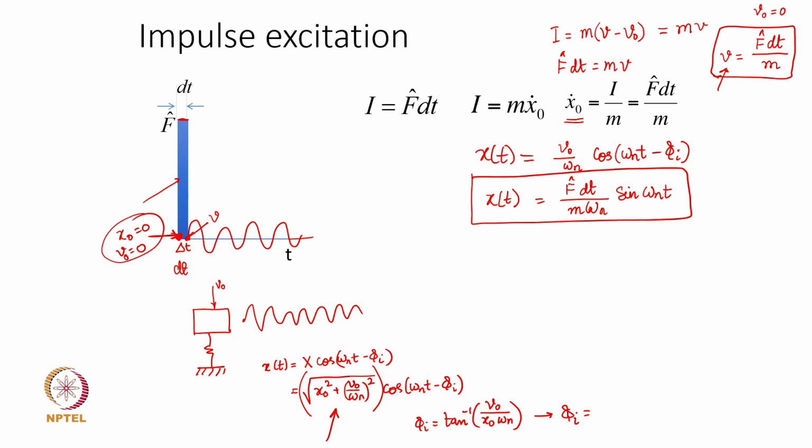The finer the dt value, the larger the amplitude, because this value is your amplitude. For the same f cap, if you reduce that delta t, the amplitude will rise; the larger you take it, the more it will reduce. That is how the response can be obtained for a solitary impulse. And it is important that we have assumed we are going to use these impulses one after the other, of different amplitude f, to represent an arbitrary excitation function.